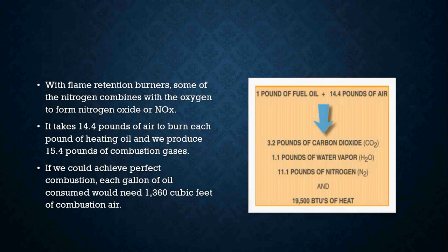So we always go for practical combustion. What's practical about it? What can we do to get it as high as we possibly can without having a constantly sooted-up burner, damaged parts, and having to come back every other week to clean it, set up the nozzle and the electrodes again, punch out the boiler, and all that other stuff.